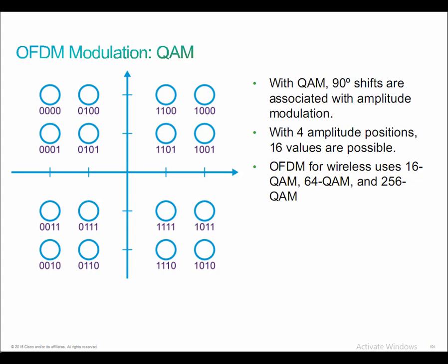All right, with 16 QAM, that allows 4 bits to be coded by a single symbol. That's 500 kilobits per second per carrier, which gives us 24 megabits per second total, right? Now, like I said, there's 64 carriers, but we're not using many of them, right? There's a few of them that are used for other purposes, as I mentioned before.